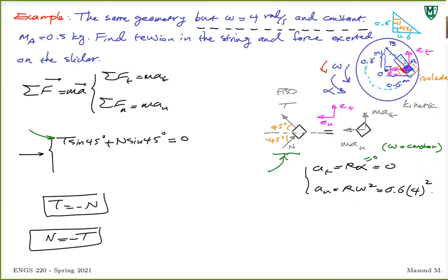You have two options. You either flip the direction of the force on your free body diagram and solve the problem again, or just continue solving the problem. Remember, whenever you're dealing with that force that you found a negative value for, you have to plug in the negative value. Later on, let's say you have something based on n, and from the second equation you get 3n plus 5 is equal to something. Remember to plug in the negative value for n. For instance, if you got n as minus 10, remember to plug in minus 10. Just some random number.